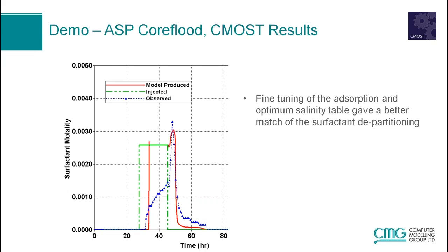Now remember, in GEM, the phase behavior of the surfactant is controlled by the solubilization ratio curves. In this example, since we used a constant IFT input from the lab, we didn't really change those curves. That's why we don't see a good match during this ramp up, but I'm fairly sure we could get a better match if we changed that input IFT data.